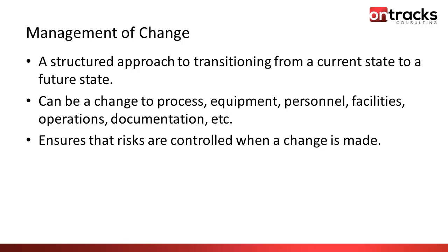Your procedure should also include technical information, any impact that the change might have, including a risk assessment and a HAZOP. Management of change should include correct authorization for that change through some sort of review process, change approval board, authorization process, anything along those lines.